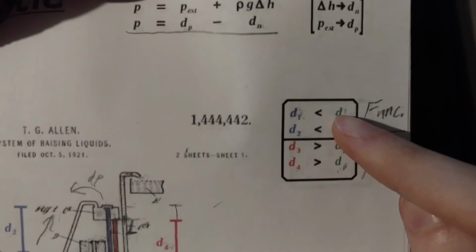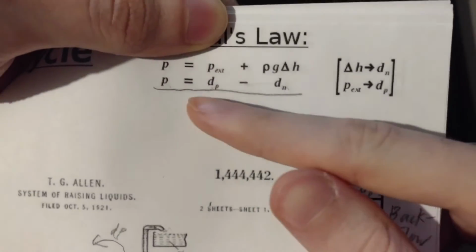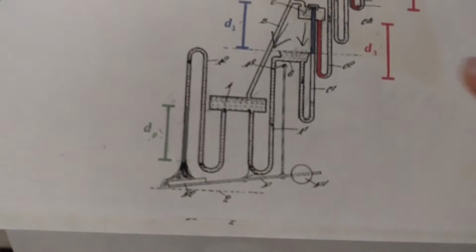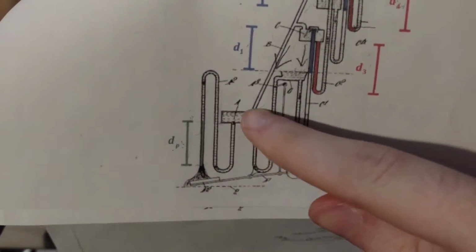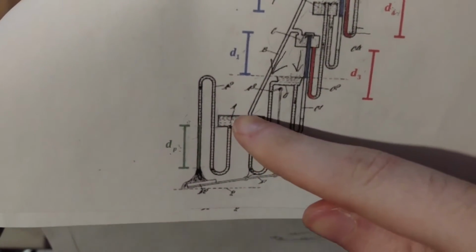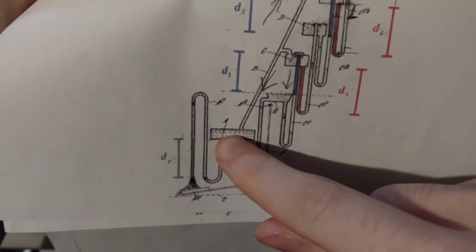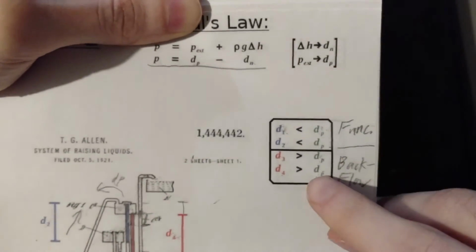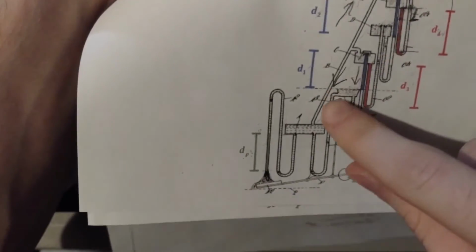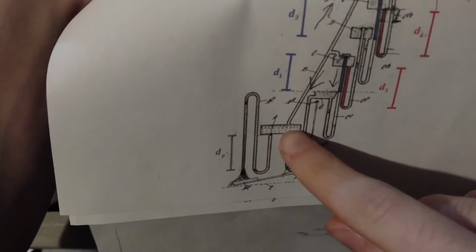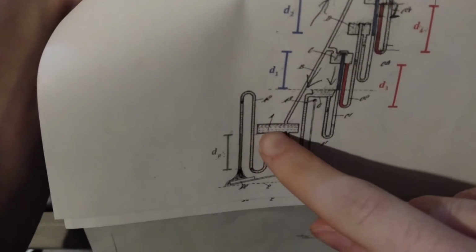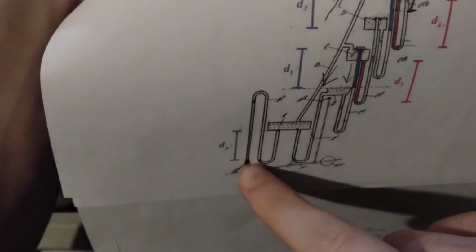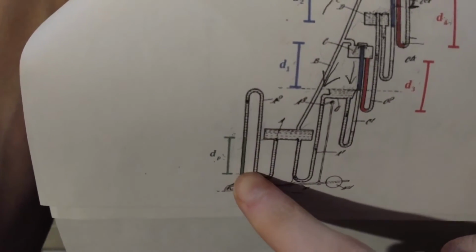Okay, so dP is the external pressure, or in other words, the pressure coming from this operating tank here. The pressure that's generated inside the operating tank, whether it's pulling or pushing, is being shoved up through this air tube into these two closed containers, and that's what your dP is, right? And that dP comes from the vertical distance between the operating tank's water line, where the water is inside of it, all the way down to the end of the siphon.